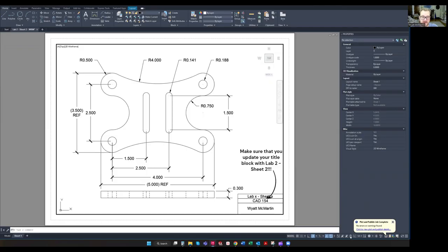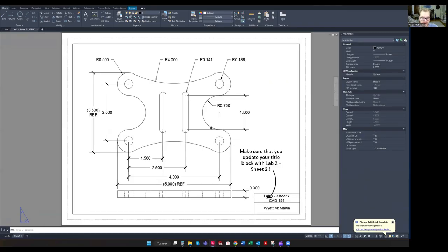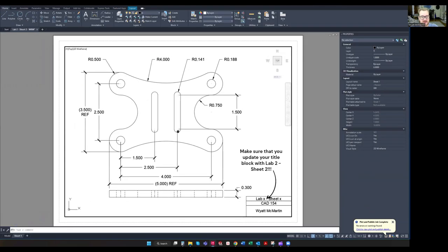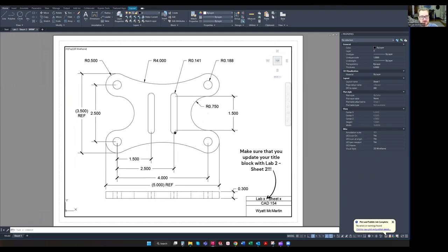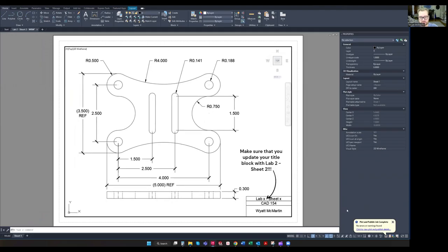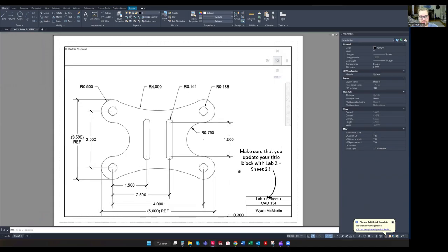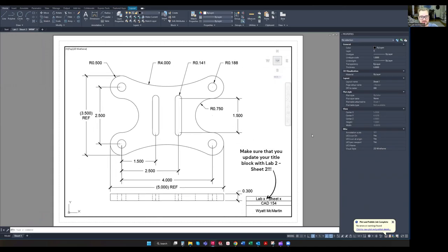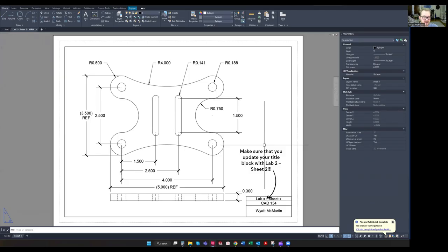You have to unlock it because remember we locked our viewport, so we're not able to pan the model. But if you unlock it, then you can kind of place it a little bit better on your page. The only thing is we have that border, so make sure the border is not showing. If the border is showing, I will take points off. Go ahead and lock. If you feel that it's safer to just move it around in model space, then go ahead and do that.